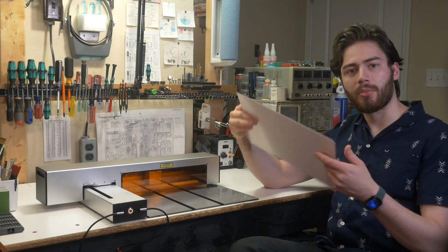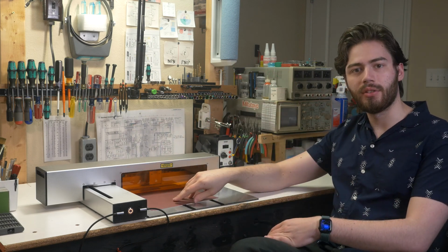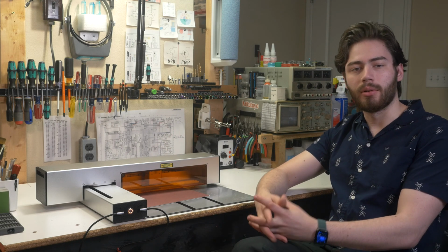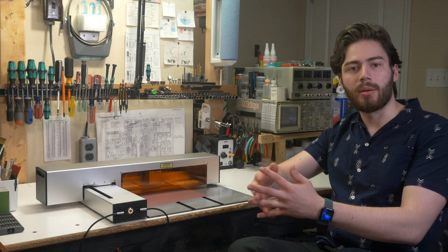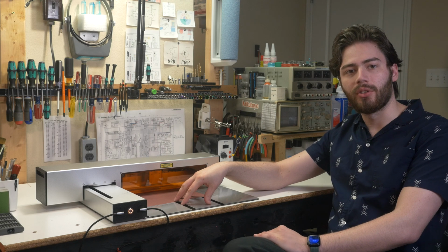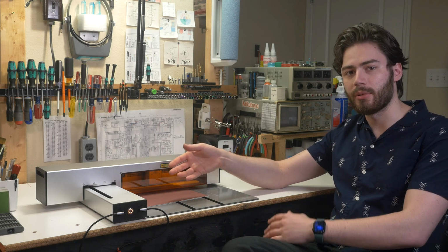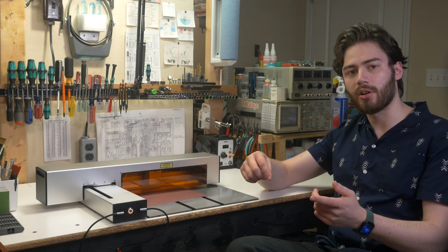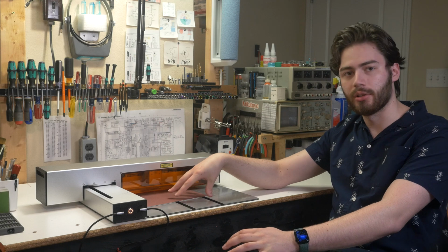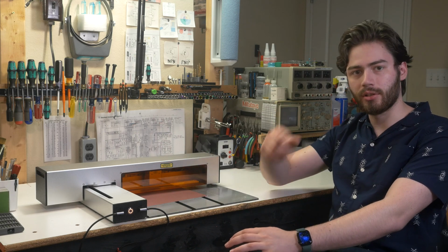Now, it sounds like matte board has lots of laser cutting potential, but you won't find it in the Optic starter material library. So, how do we figure out what cut settings to use? Well, the first step is to select some parameters for a test pattern. This test pattern will be a grid of small squares, each with a different combination of parameters, which, when you're testing cutting, are usually speed and number of passes. This pattern will help us identify the best combination for our particular material. Let's go take a look at Lightburn to see how we can easily set this up.